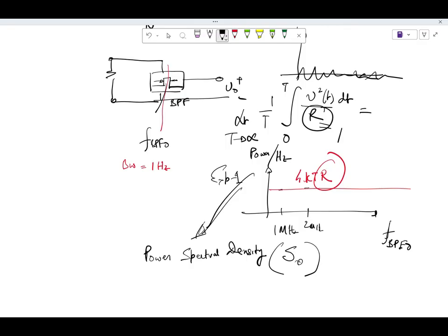The reason the nomenclature stuck is that there is a relationship between this and, if time permits later on, I'll try to prove that one. So as it turns out, this is the frequency domain representation, right? There is a time domain representation of this, and that's called autocorrelation. You can show that power spectral density, the way we have it, is totally not intuitive with the way I have talked about till now. You can show that power spectral density is the Fourier transform of the autocorrelation. Okay, you have done it in your communication courses, fine. If not, just take that from me.